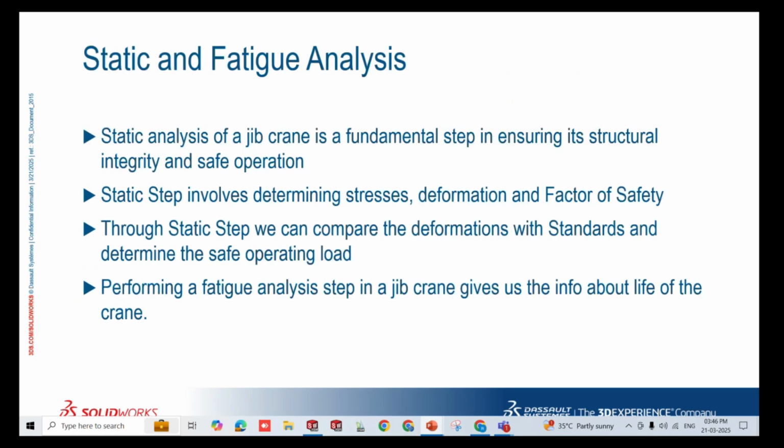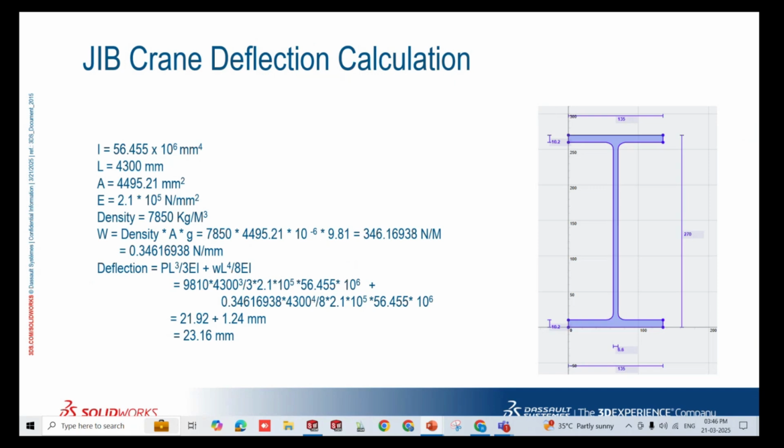Now, we have performed static analysis and fatigue analysis. So what are those? Static analysis of a crane is a fundamental step in ensuring structural integrity and safe operation. The static step involves determining stresses, deformation, and factor of safety. Through the static step, we compare the deformations with standards and determine safe operation. Performing a fatigue step on a crane gives us information about the life of the crane. This is the hand calculation which I have done.